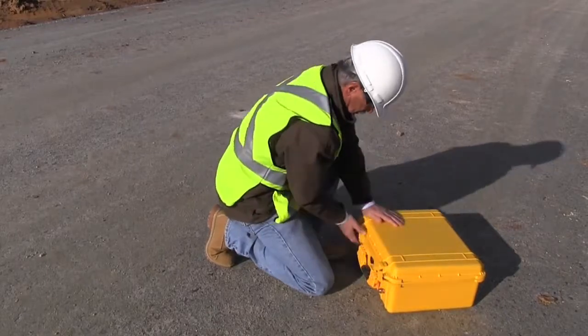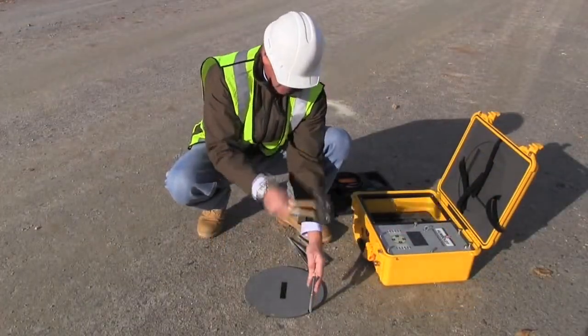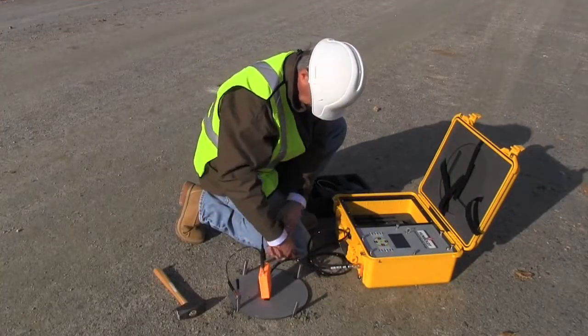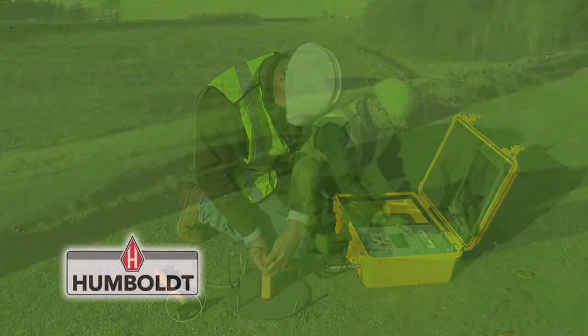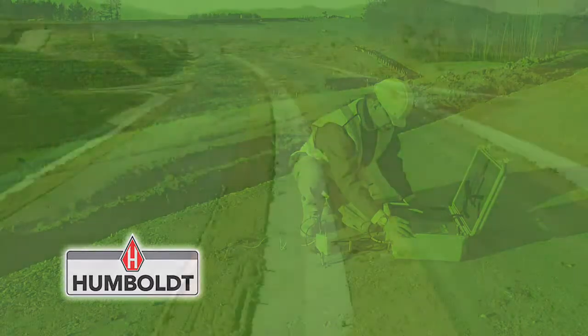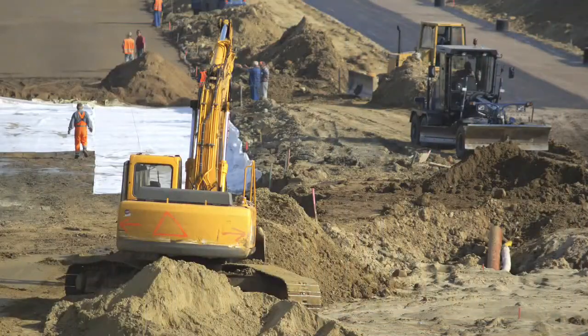The nuclear-free EDG allows you to quickly and accurately make determinations while freeing you from the regulatory constraints of nuclear gauges and the intensive labor and consistency concerns associated with sand cones. The EDG can be used anywhere there is a need for density measurements, including roadbeds, foundations, excavations, retaining walls, and earthworks of all types.